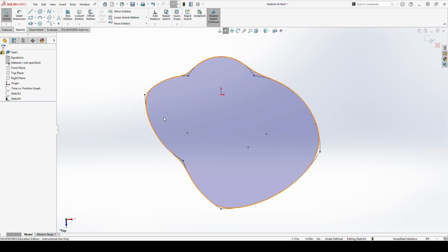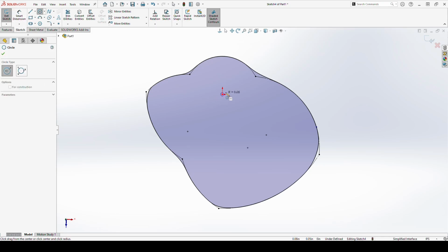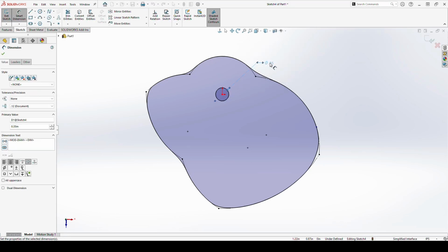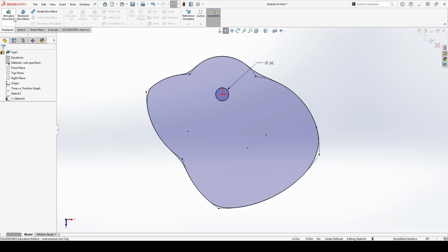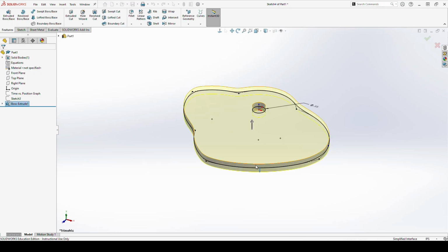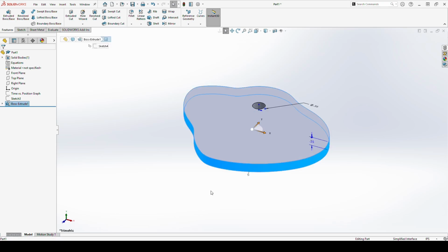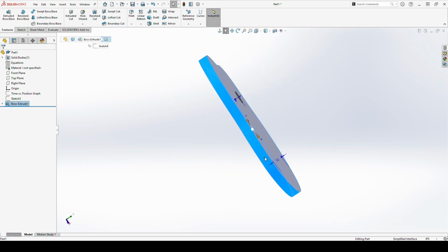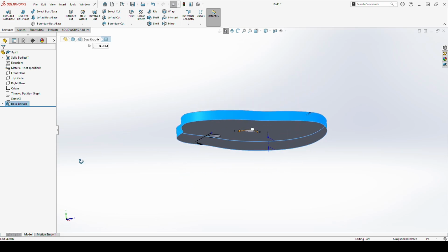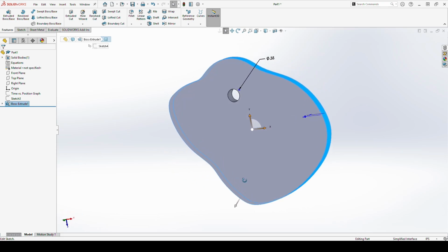As you can see, when I click on the line, it selects the entire line at this point. So it is one entire continuous line. I'm going to go ahead and add the rotational device, the little hole in the cam that we're rotating around. Once that's done, I go to my extrude and set up my extrude. You're seeing that this entire piece is one surface. I clicked on it, and the entire thing is turning blue. The entire thing is one connected surface.